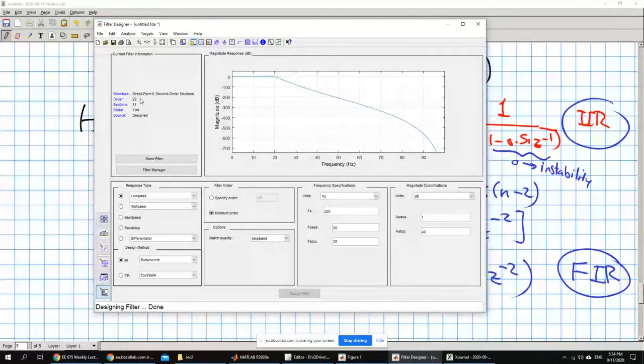Is that clear? First of all, do you know the difference between FIR and IIR now? Yeah. We got it. Okay. Do you know the reason for the transient that happened at the beginning of the signal? Whenever I do filtration, you expect to have transient. Do you know the origin of this transient and how long it will be? You know the theoretical basis for that?